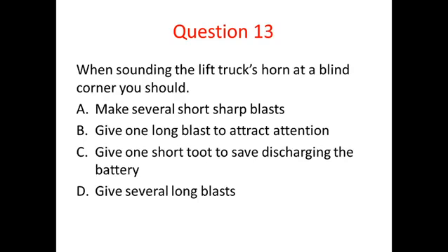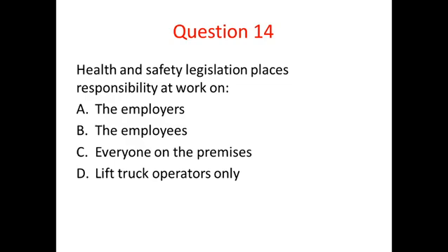When sounding the lift truck's horn at a blind corner, how should you go about doing it? Nice and simple. Beep, beep, beep. Several short, sharp blasts. That will be an effective way of notifying people of your presence.